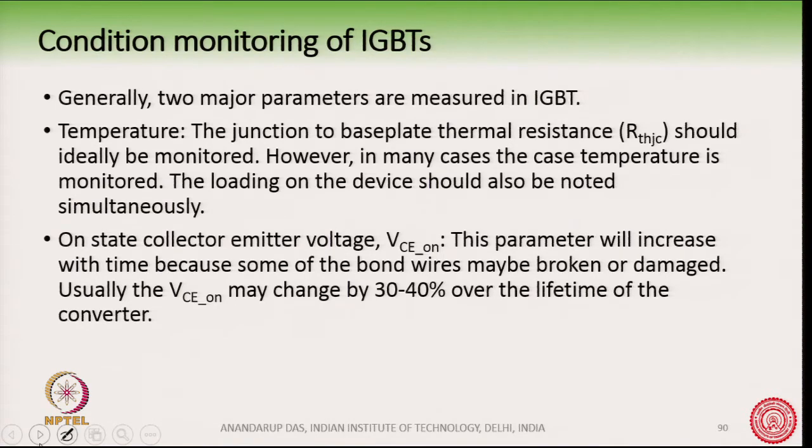The temperature usually will increase for the same loading condition. The temperature will increase over time in an IGBT, under the same loading condition. And why is this so? Because over time the bond wires inside the IGBTs start to lift off and cause additional heat dissipation over the existing bond wires which are present. And so, the temperature of the chip or close to the chip will increase.